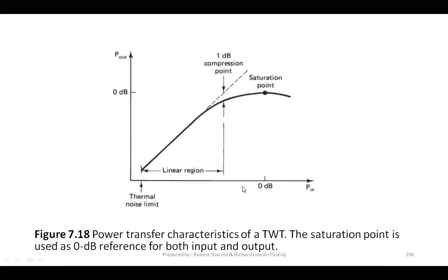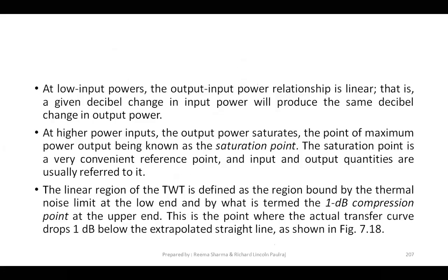As my input power increases, this linearity is lost. You can actually see that the wave has a slight change from its linearity property. At higher power inputs, the output power saturates, and the point of maximum power is known as the saturation point. So this point is a convenient reference point, and input and output quantities are usually referred to it.